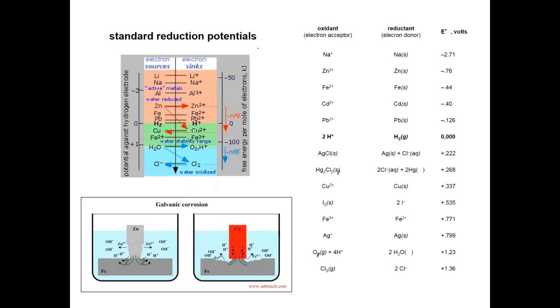To characterize these materials, of course, one can visually characterize them, but quantitatively, and what we do in our lab, and many labs in particular, to predict and to do a forensic analysis of corrosion, is use electrochemistry, which is one of the methods that I'll outline today. Here, what you can see is a 3-electrode cell setup, which can be done in a potentiostat galvanostat setup, or an instrument that has capacitive properties where we can do electrochemical impedance spectroscopy.